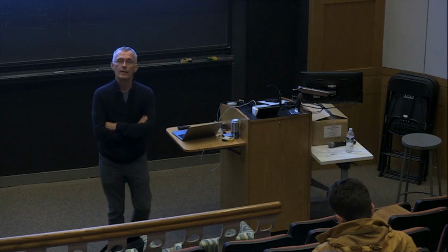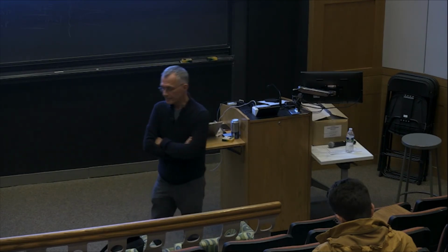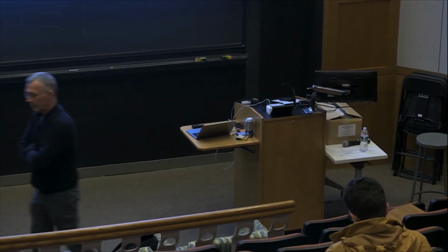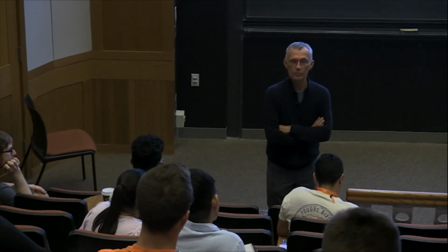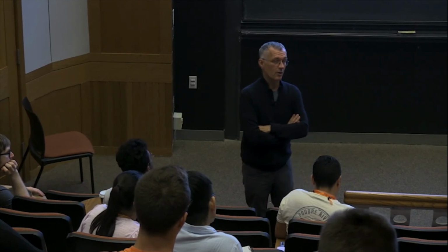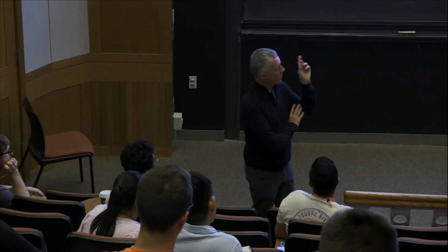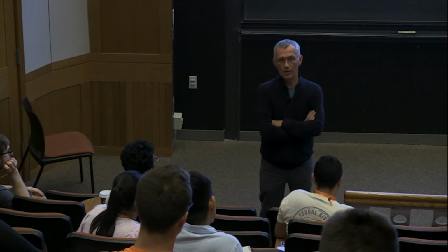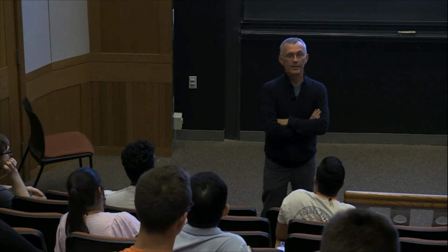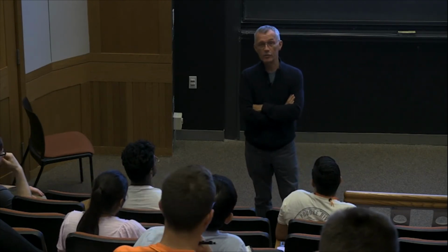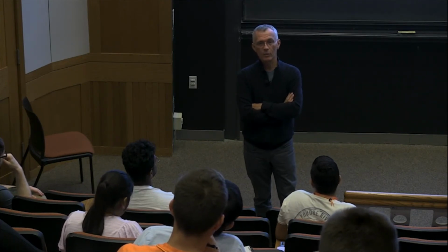Yes. Okay. The question is, what about NOx? Whatever you do today, as soon as you talk about an H2 burner, people will tell you, you control NOx. It is not easy, but for the cases I've shown you, we keep NOx under what's regulated. We can do it. But it is obviously very dangerous. If you start having diffusion flames, then you don't pass for NOx. And so NOx is going to be one of the main problems.